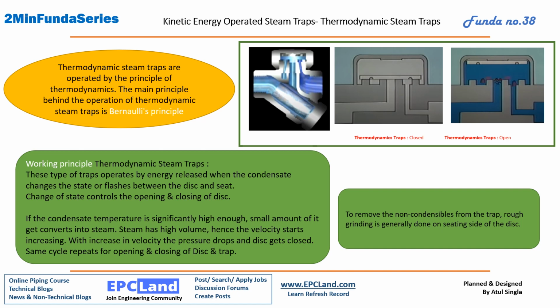How it operates: when the condensate comes, it lifts the disc upwards and it opens up. When it is in the open position, at some point, when the temperature of the condensate is significantly high, it starts changing its state into steam. A small portion gets converted into steam. When it gets converted into steam, the velocity of the condensate passing out increases. When velocity is increased at this section, then pressure starts dropping. When pressure starts dropping, the disc starts coming down. Then the steam starts accumulating at the upper portion of the disc, which further pushes the disc and closes the trap. So this is the basic principle where the disc opens or closes based on change in state of condensate.